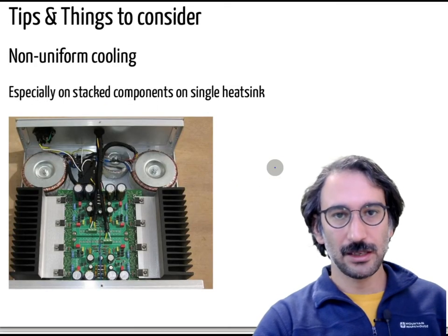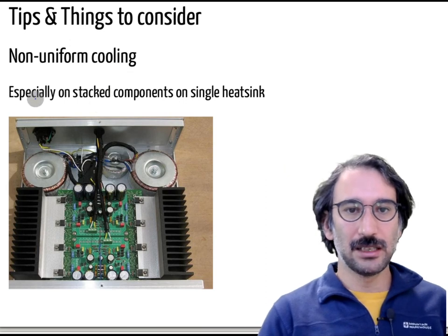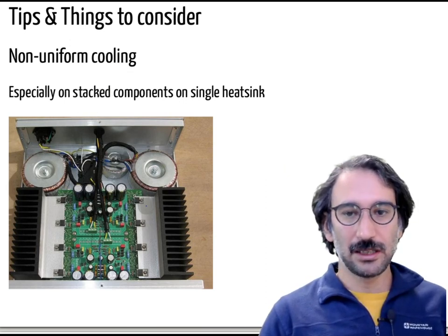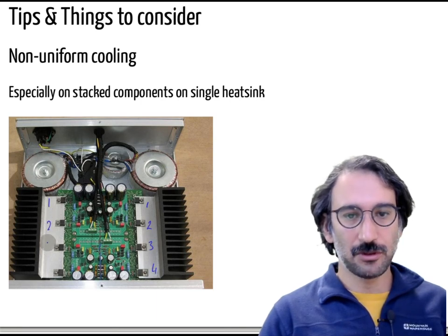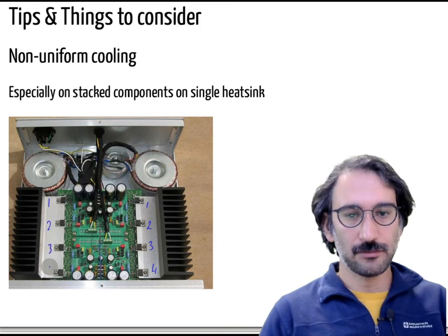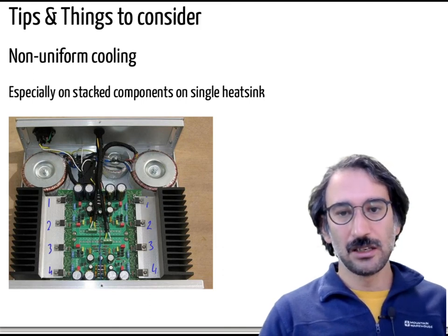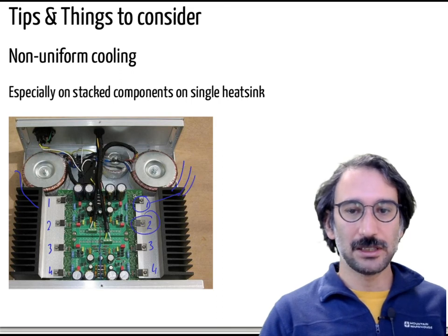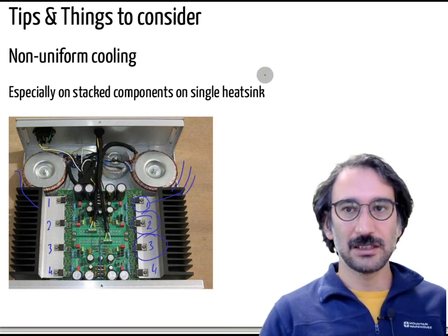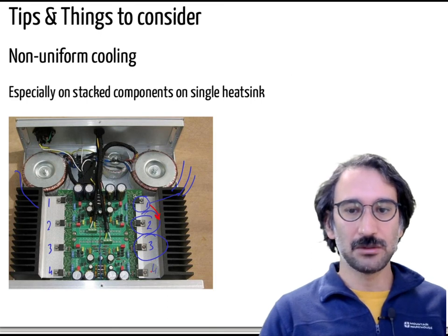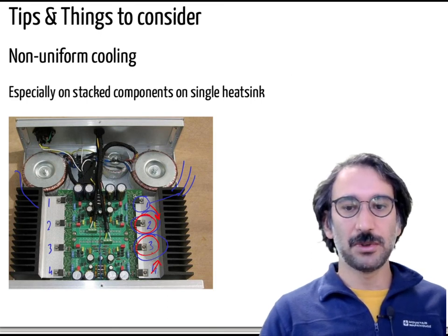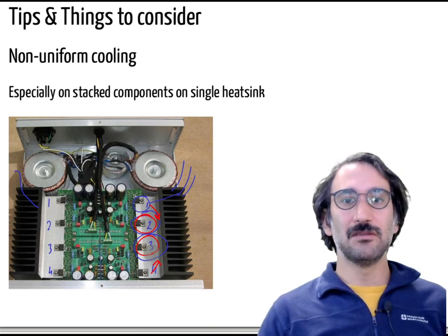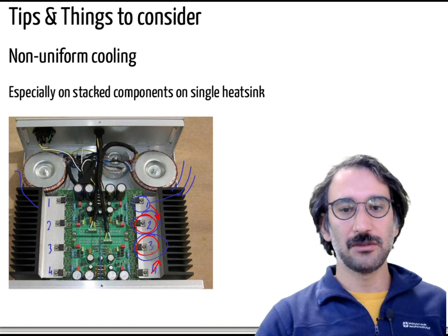Okay. And again, you need to be careful about paralleling devices. Here probably they connected 4 MOSFETs, or I don't know, another 4 here. The one at the end doesn't have any neighbor material here, so it can dissipate the heat just from that side. But for the ones in the middle, there's some heat coming from that side, and also some heat coming from that side. So the operating temperature of the switches in the middle will be higher. So you need to be careful about those things.